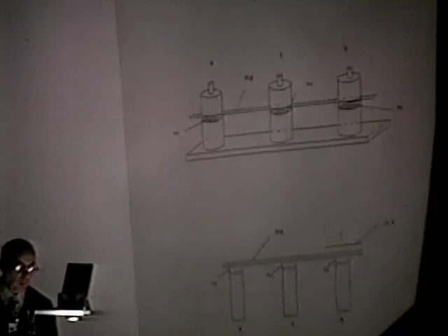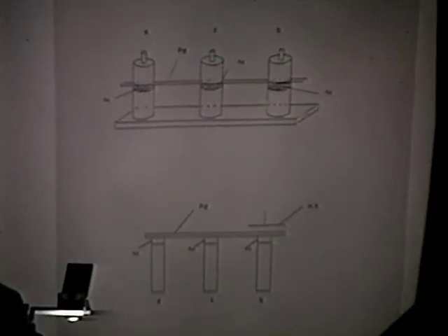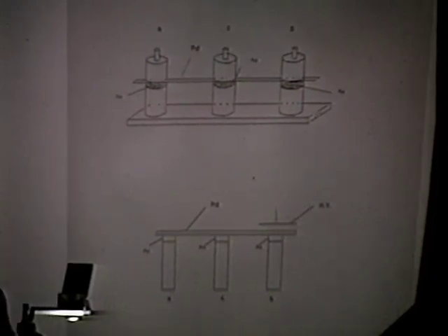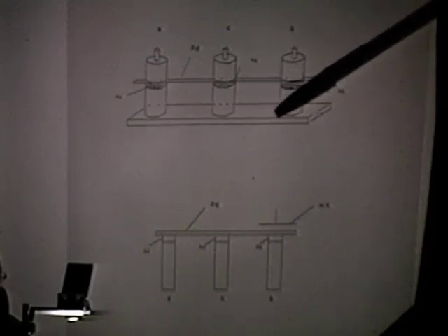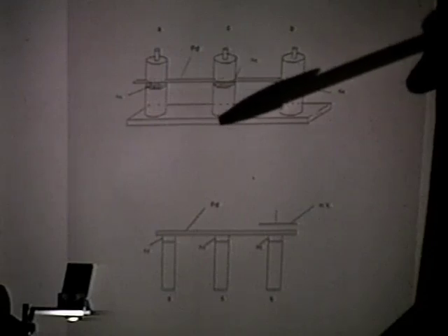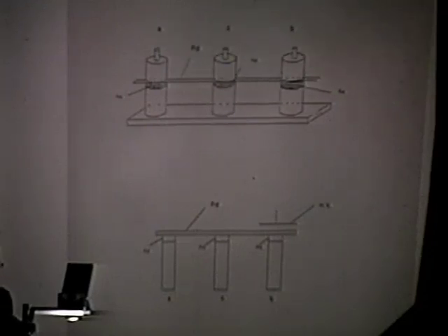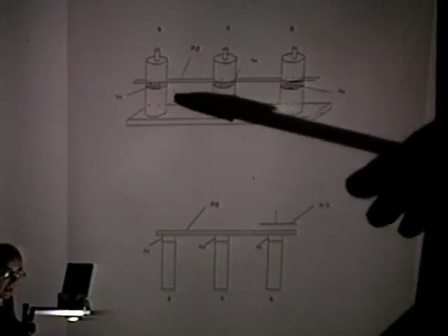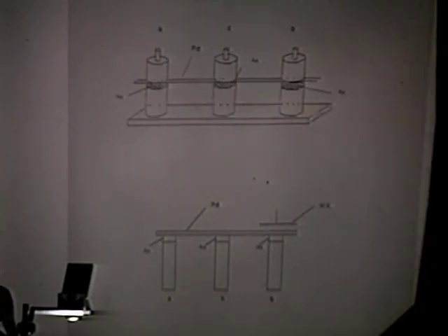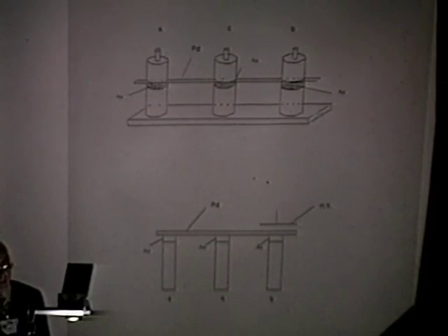We are now considering the third type of perturbation we were applying to palladium sheets. This figure is giving a schematic account of the design of the experiment. The sample was constituted by a strip of palladium, thin about 50 microns, wide 2 millimeters, and the length was about 10 centimeters. This was assembled inside this holder. The holder was having gold contacts in these 3 points. The sample was placed inside a closed vessel in which we could apply a pressure of deuterium so that the